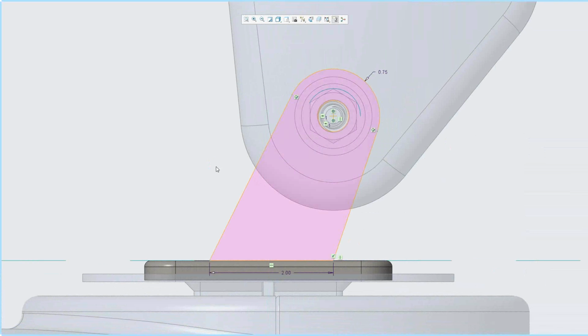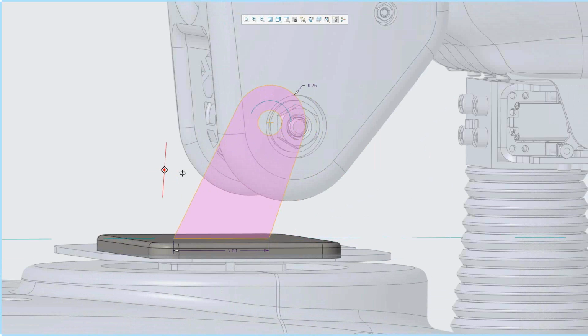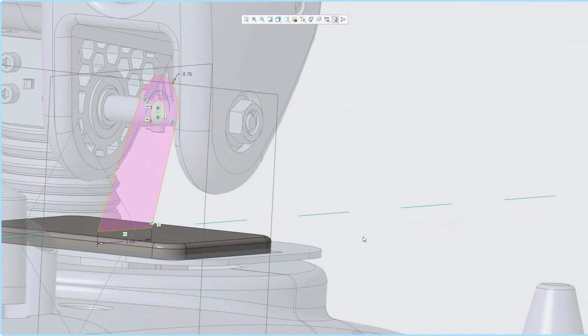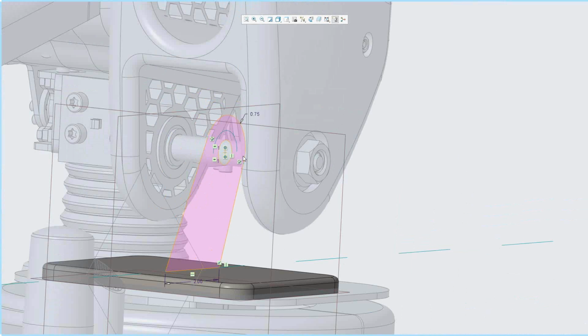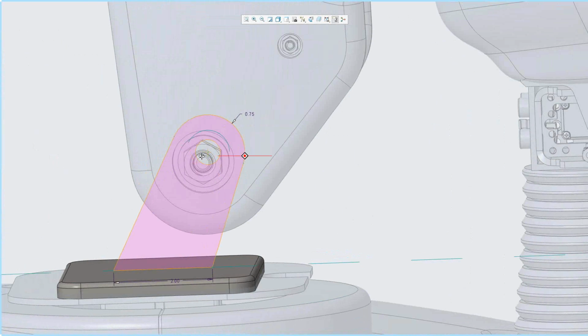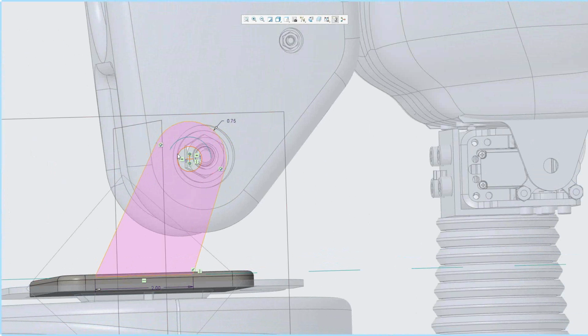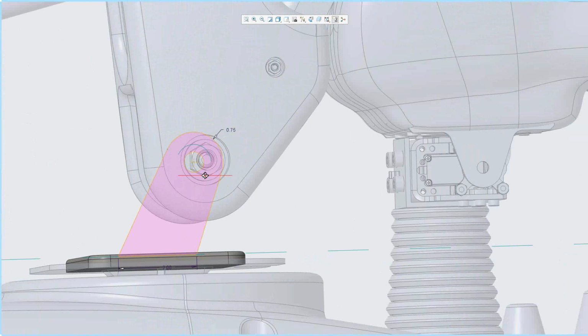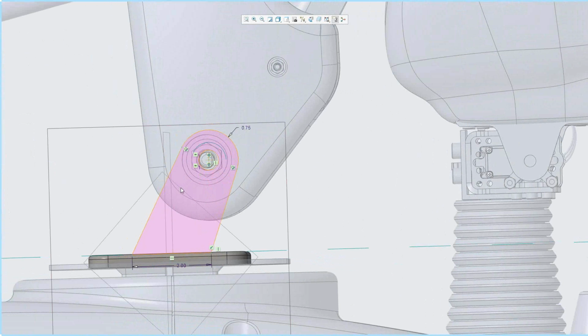So in order to show what's going on with the sketch plane clipping, basically what's going on is this. Right now my sketch plane is in the middle of this geometry right here, right around this pin, right? And ordinarily, if I was going to view the sketch plane in 2D, I have all this geometry here in the front obscuring my sketch plane and any geometry or references I want to select behind it, right?